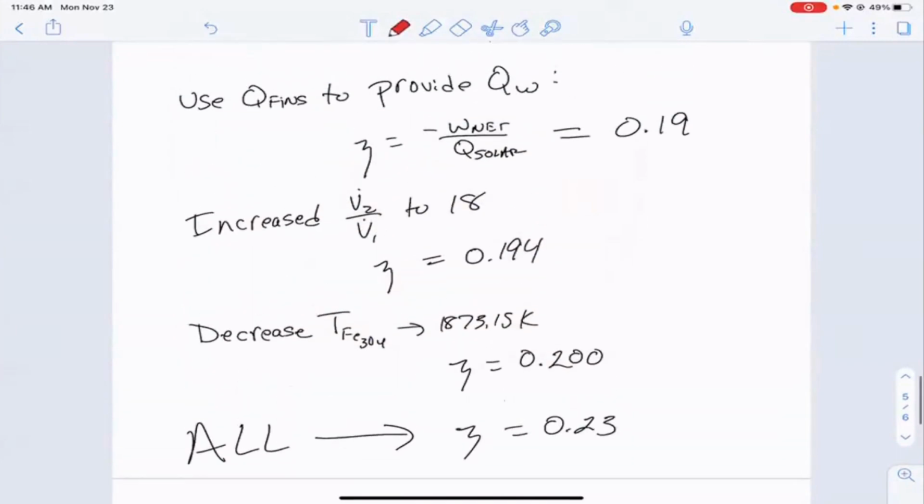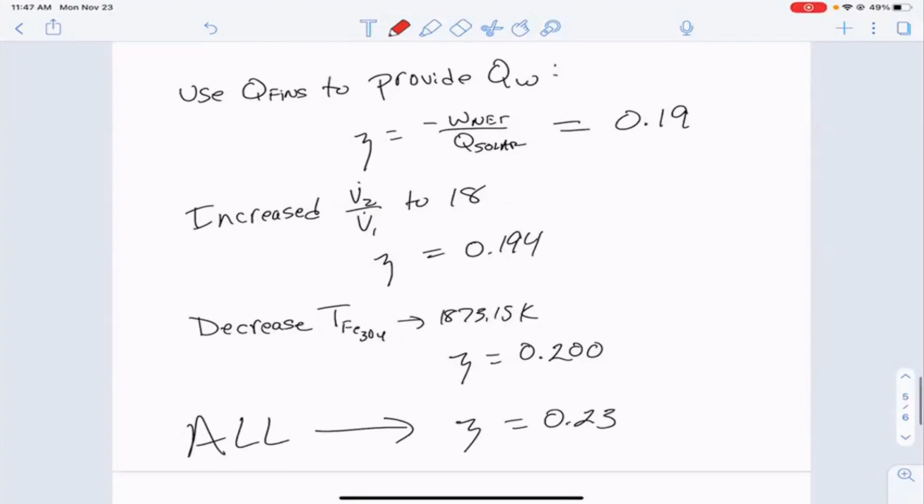And I think this one is pretty easy to do. In an Otto cycle with hydrogen, this one is also doable. Compression ratios for internal combustion engines on hydrogen are actually higher. If you just did a little bit of background reading, 18 to 20 is not unusual. So that's fine.